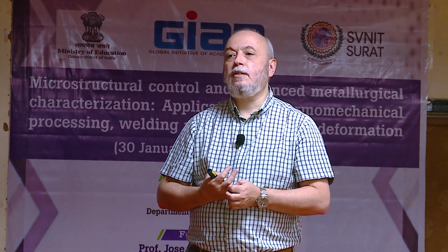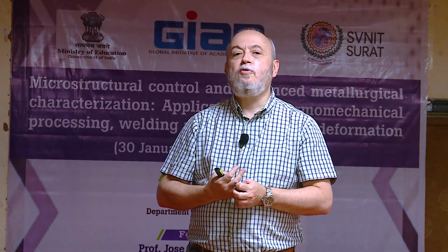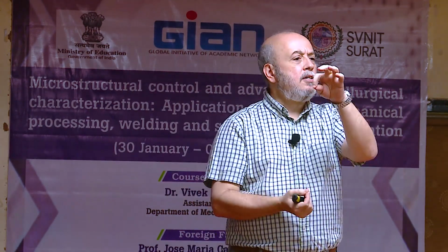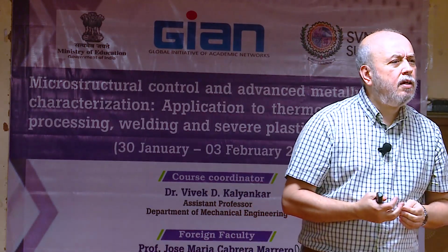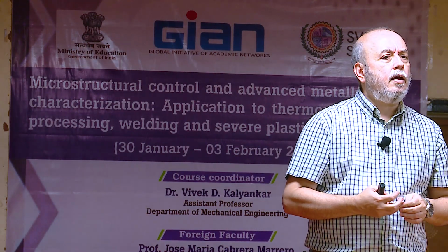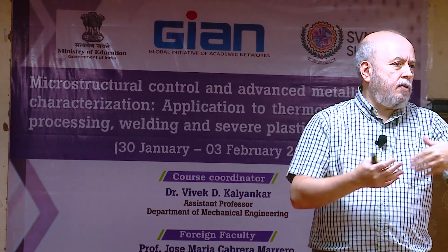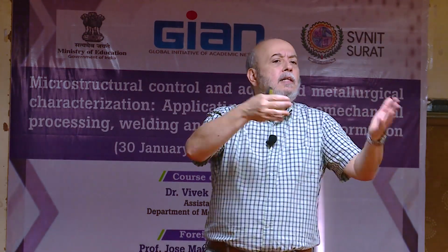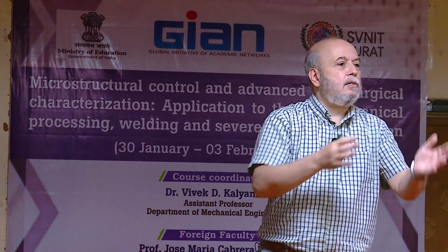Who works in a metal laboratory? How many of you have done a tensile test? What is the typical elongation that you get? For sheet metal, 20 maximum. In terms of elongation, in percentage? Yeah, 20, 30%, something like that, plus minus that value.